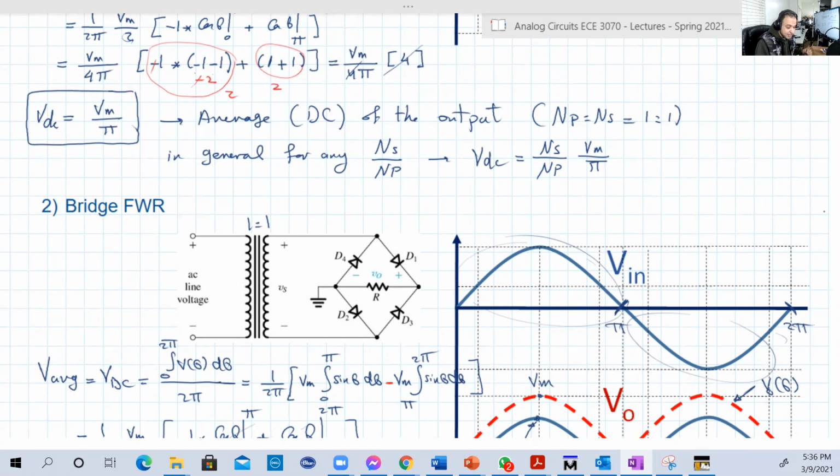But the center tap rectifier as an idea has other implications or advantages over the bridge. We can use a bridge with the idea of the center tap transformer to produce negative and positive DC at the same time. So with the input AC, you can have a sustainable positive DC output and another sustainable negative output at the same time for two loads, one positive and one negative. It's a really good idea, but by itself, the bridge can beat it. It has many advantages.